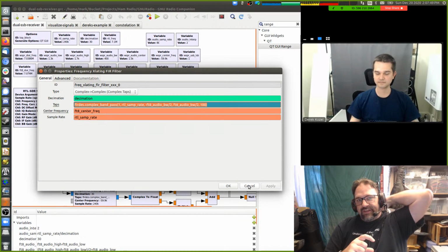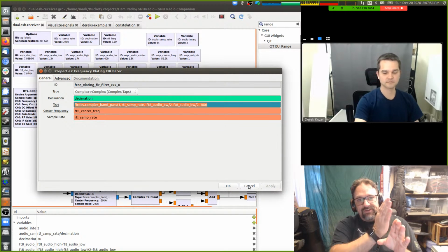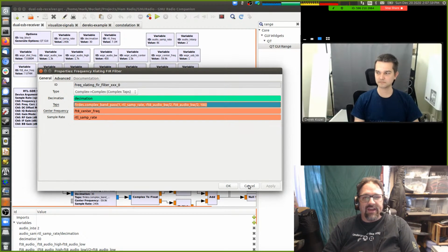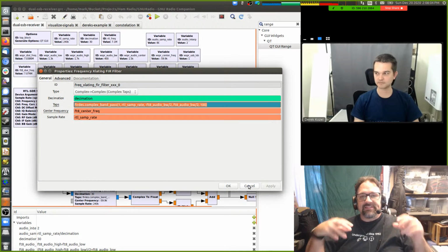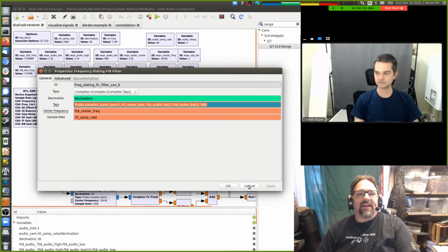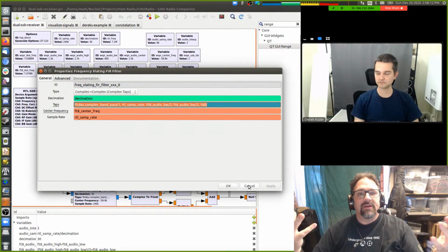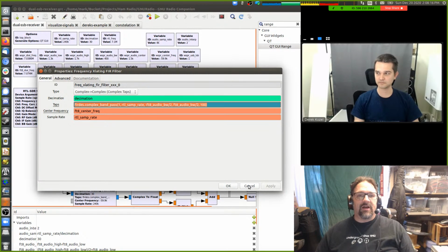And so this is a function that makes FIR filters super efficient, because you just have to do however many single instructions as you have buckets in your FIR filter, instead of having to do a multiply and then a move and then an addition and stuff like that. Some of those DSP functions are the kinds of things that you don't do very often in normal computing, but when you're doing signal processing, it's the kind of thing that you do a lot.